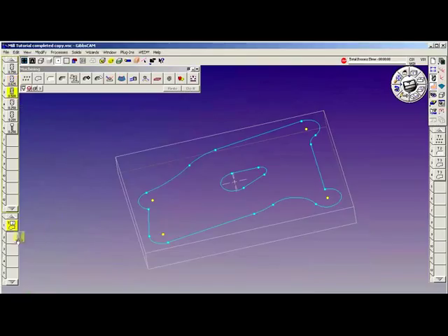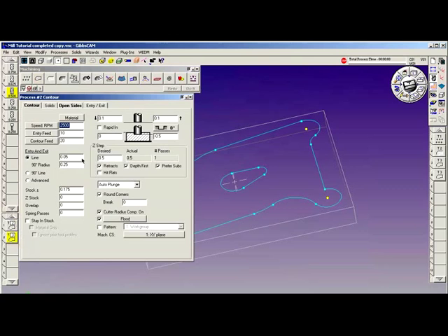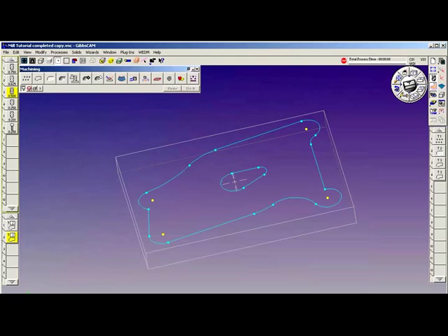I bring tool number 3 down to process tile number 2, bring down the contour tile, and as you can see, all the values are there. Everything's set for me to do it. The only change I'm going to make is make this 150 thousandths. So it takes an extra 25 thousandths off the previous cut, and I'll add an overlap of 30 thousandths. Close the dialogues. I'll go to top view,